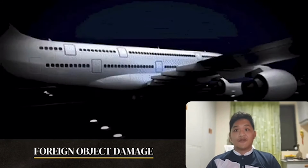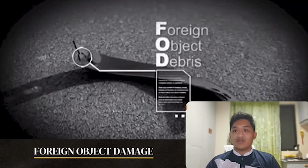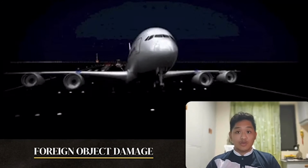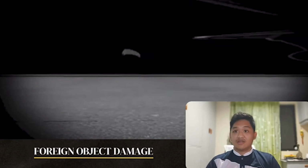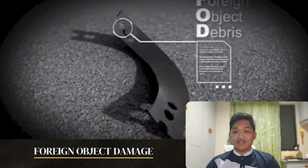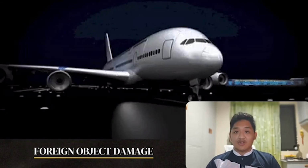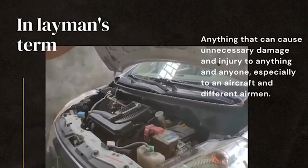It's possible for foreign object debris to be created when a jet blast propels a small object and then collides with something else along the projectile's path, like bolts and screws, pens, tools, PPE or personal protective equipment like gloves, goggles, boots, or helmets, and many items that may be considered to be FOD. It can also be in a liquid form like gasoline or hydraulic oil. Basically, anything that can cause damage to an aircraft or hurt any airman is an FOD.